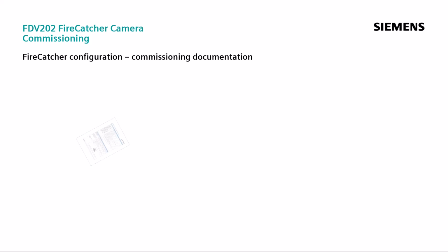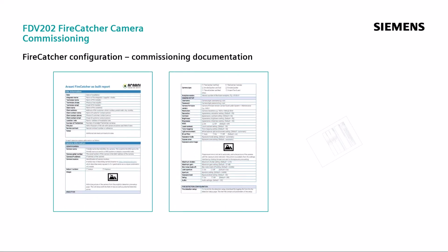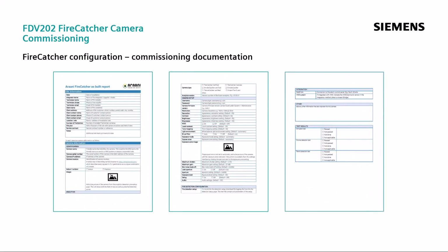As the final step of the installation and commissioning process, it is recommended to document all settings previously defined in a protocol. A template for this can be the Maintain as Built document. On the one hand, this can be used as a handover to the customer, but also as a reference for later inspection within the scope of maintenance work. Please also note that some countries have local regulations determining the level of documentation.